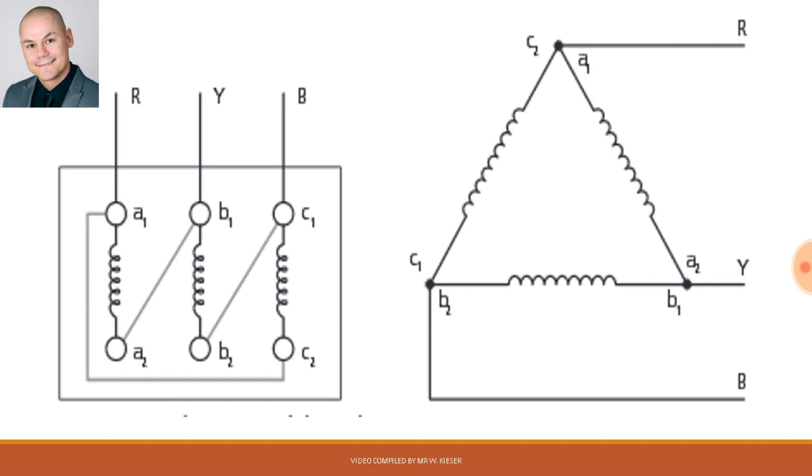The next type of three-phase motor that we get is a delta connected motor. Here we've got a terminal box with 6 studs, 3 lives, red, yellow, and blue. And we find that we still have our 3 stator coils between the studs, A1, A2, B1, B2, and C1, C2. Now, in order for this to be bridged as a delta connected motor, A2 and B1 must make contact, C1 and B2 must make contact, and C2 and A1 must make contact, and this would make it delta connected.